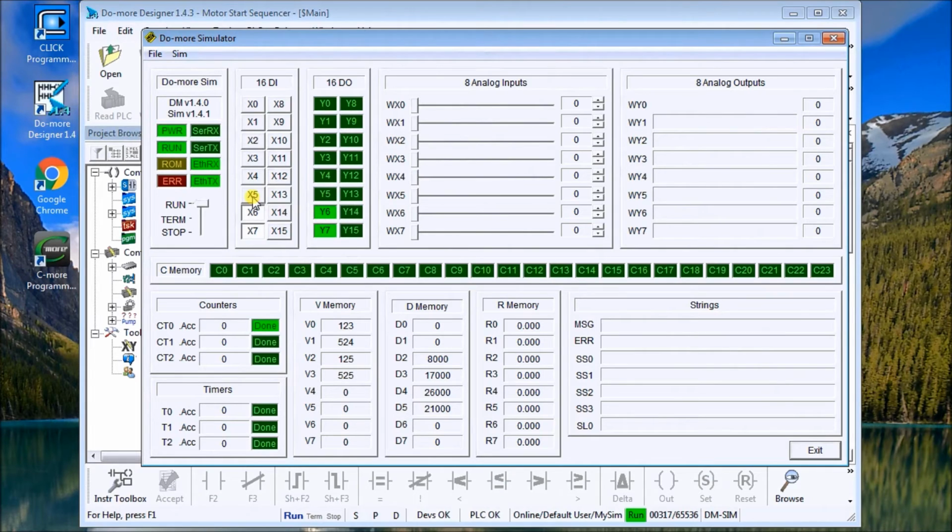But what happens is if I turn on things quicker, so 5, 4, 3, 2, and 1, you notice there's a delay now. So you'll see between each one, it's going to be delaying 5 seconds until they all come on. Now turning off motors is not really a huge issue, because it just cuts off the current. So we can just turn them off, and you see they go off instantly.